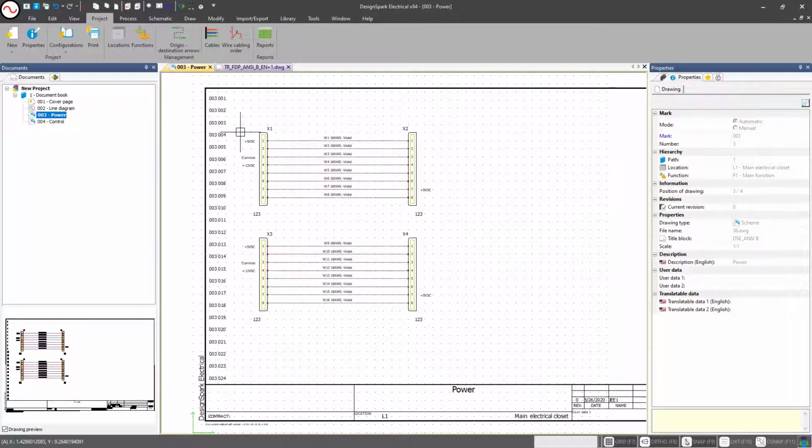The nice thing with this is by setting it up in a manner like this, now that my title block is set up with this kind of information, I can also drive the mark automatically based off of the row and sheet, or the sheet and row, for my connectors and my wires. So I don't have to worry about assigning default codes such as X1 or J1 or P1 or W1 to my wires. It will take on the naming convention based on the row it is in. And it just helps us to identify and define the information in our schematics that much easier, especially when we get to things like our wire reports or any type of bill materials later on.